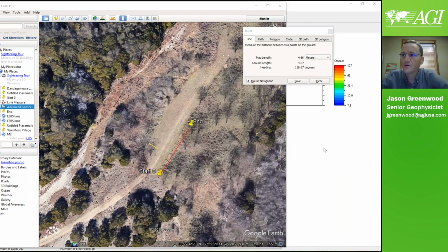Parallel to a concrete pad is generally not an issue because it's diffuse and not like a pipeline, like one linear conductor. It would tend to show up as slightly lower resistivity in the near surface. So if there was a pad parallel to a line, I would try to run perpendicular to it. But again, that pad is probably thin and like a pavement